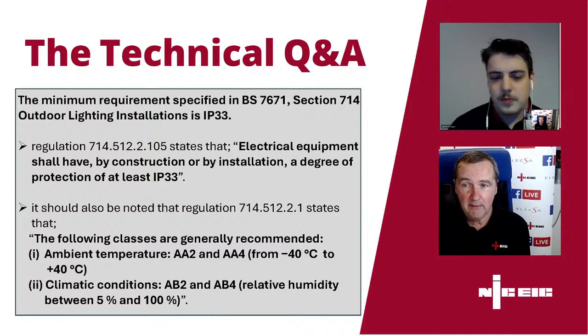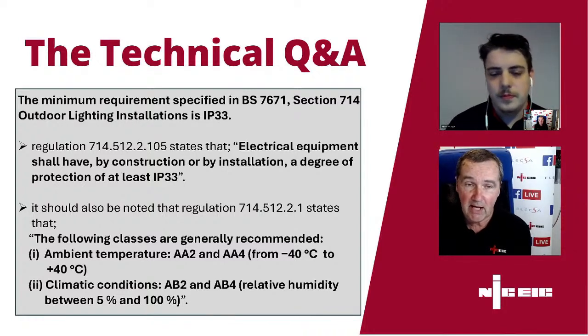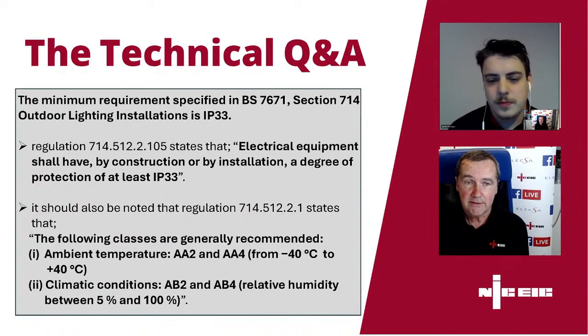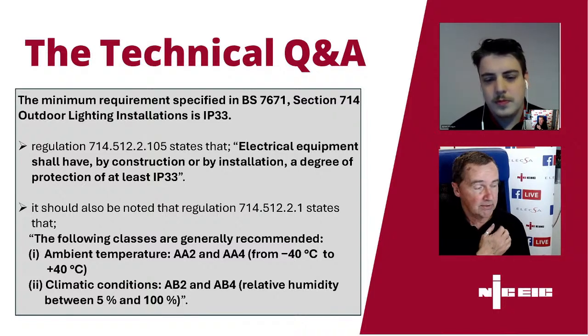So the date for the next inspection only refers to the circuits that you've talked about as being added or altered. So again, be nice and clear about what you have done and what you're taking responsibility for, and then that becomes clear. It's those things that are being used for your date for your next inspection.